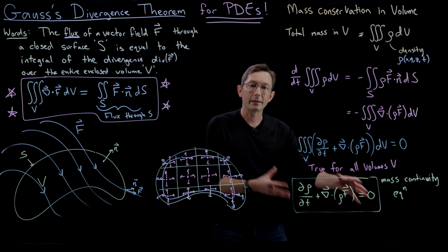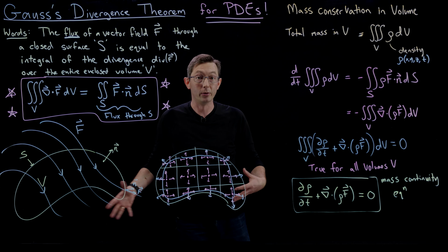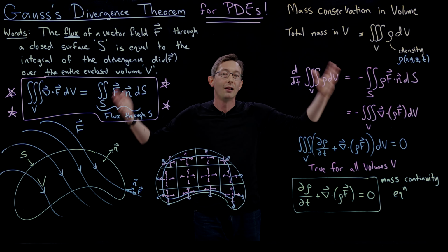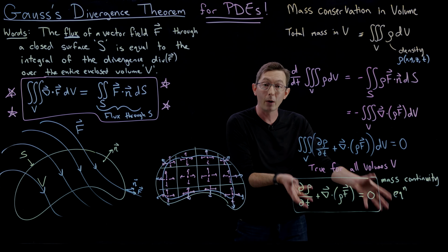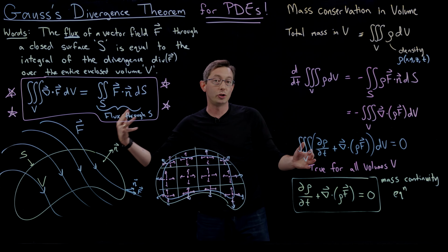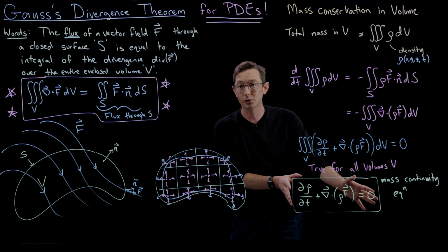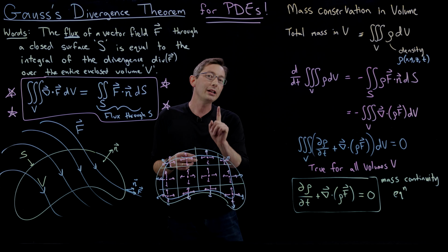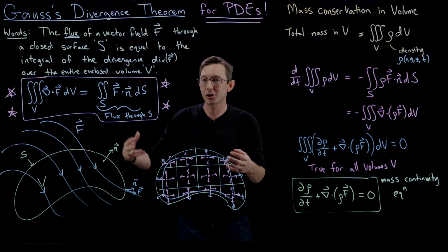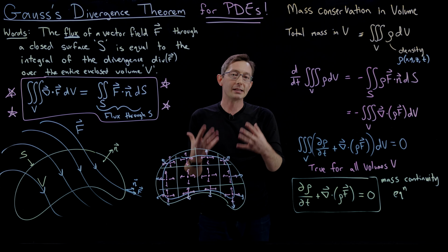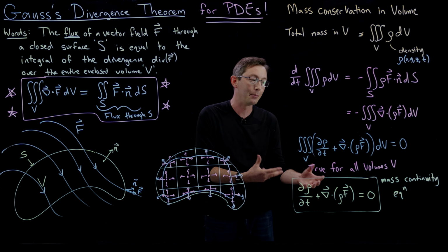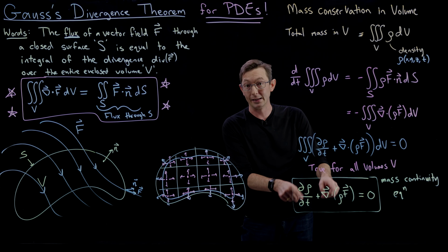This is the equation that quantifies conservation of mass in a flowing fluid, in the air. When I'm speaking, air is moving, but the mass is still conserved. In this room, mass is not being created or destroyed, and so this equation is true everywhere in space and in time. Even if I have a jet moving through, even if it's a compressible fluid flow, this is still true. It is only not true when my vector field F, or my density rho, is sufficiently non-continuous. If it has a really sharp step change in space or in time, then these derivatives don't actually make sense. They would go to infinity.